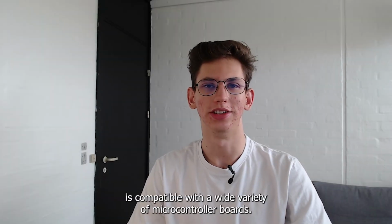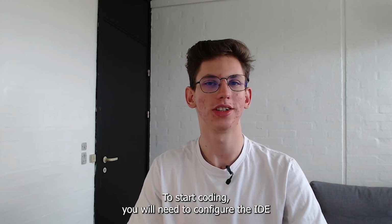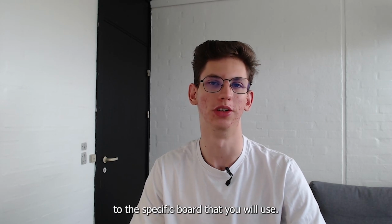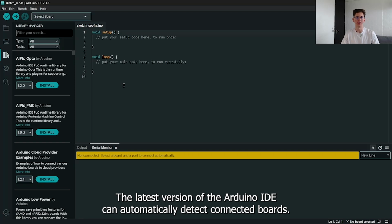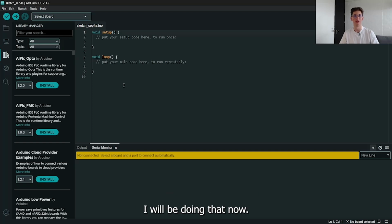The Arduino IDE is compatible with a wide variety of microcontroller boards. To start coding, you will need to configure the IDE to the specific board that you will use. Since we will be working with the TTGO T-Display ESP32, this is the board that we will be setting up in this tutorial. The latest version of the Arduino IDE can automatically detect connected boards. Simply plug in your board using a USB cable and the IDE should recognize it automatically. I will be doing that now.